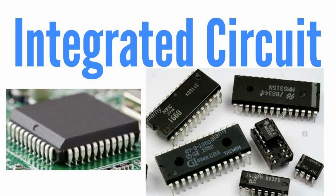2. Filtering. Function. Filters are employed to modify the frequency content of a signal by allowing certain frequencies to pass while attenuating others. Low-pass, high-pass, band-pass, and band-stop filters are common types. IC type. Active filters, often implemented using op-amps, are widely used in analog signal processing.